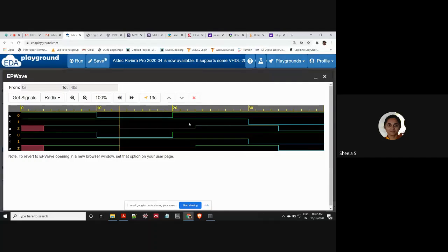Okay, and here for fall time, meaning for making a transition from logic high to logic 0, how much delay it has taken, you can observe here. And also if you are not able to see, here you can see the corresponding time where the marker is. The input is changed at 30 seconds, but the output changes from high to low at 34 seconds. Means it has taken 4 time units of delay to make a transition.